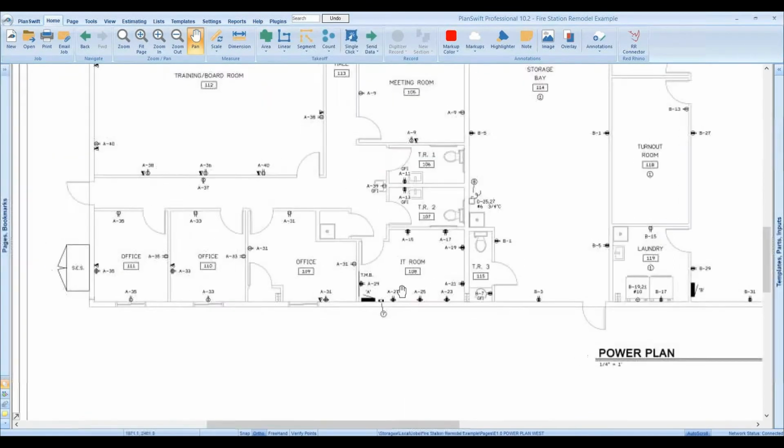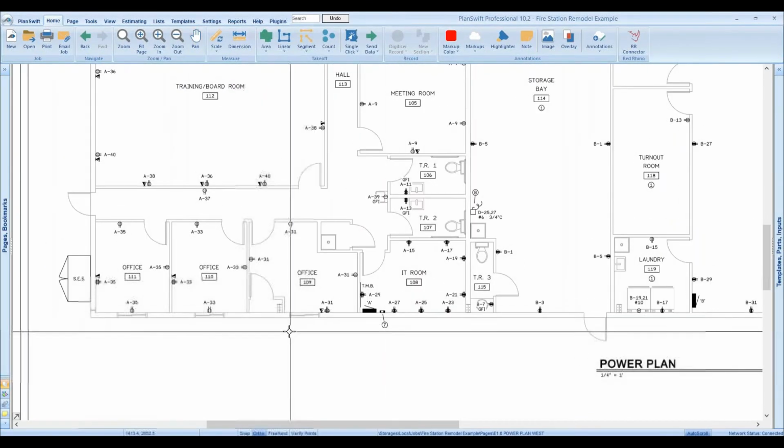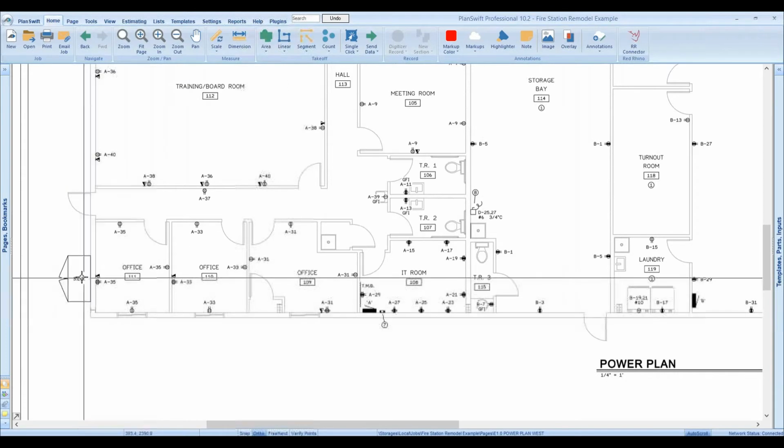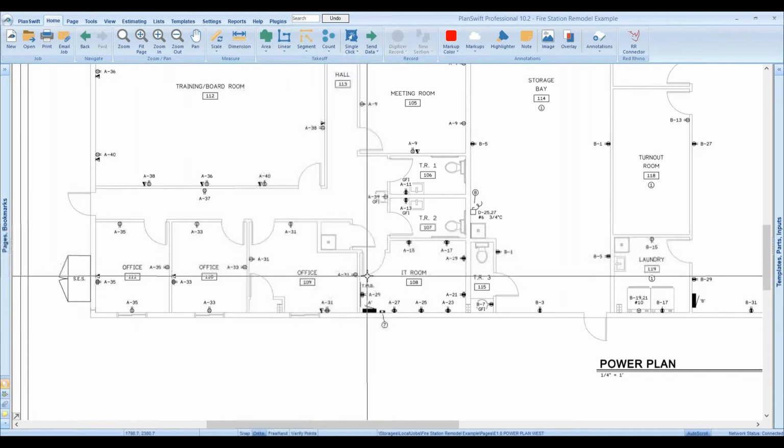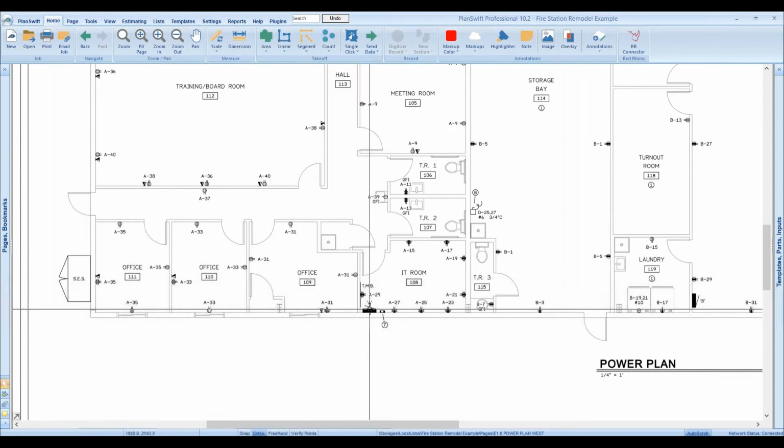Now I'm just going to explain real quick. I recommend taking off or measuring conduit at right angles. I would measure over from SES and down on the blueprint, but then you want to add for the conduit riser. You know, the conduit riser is the conduit that goes up or down. Now in this example, I've already calculated these distances. Again, my purpose is just to show you how to use the Conduit Wizard, but it starts with an accurate material takeoff of the conduit length.